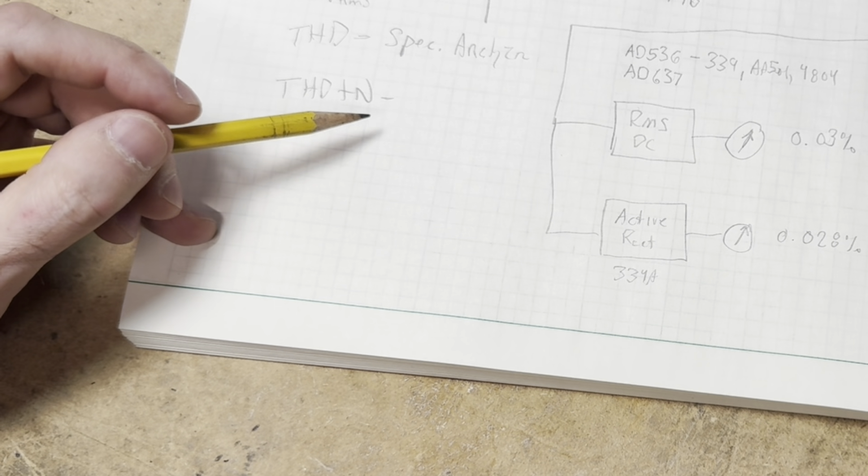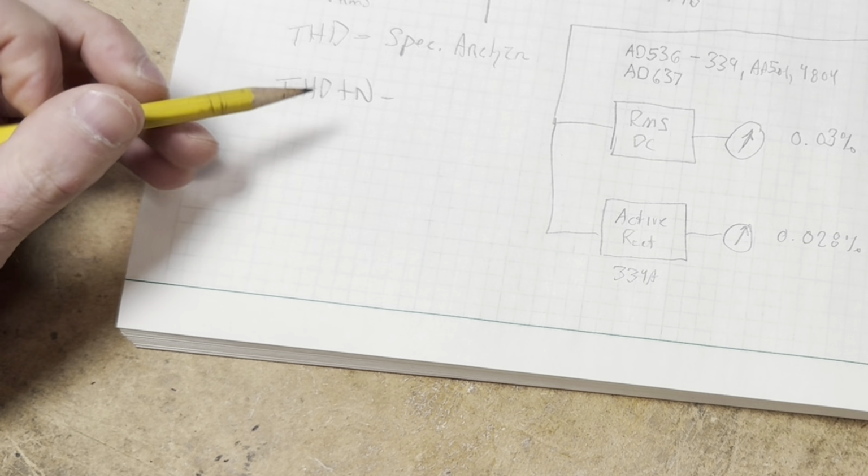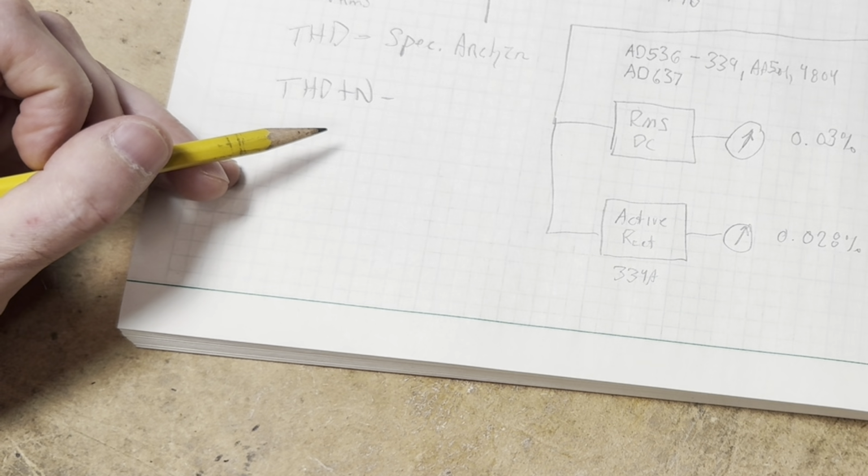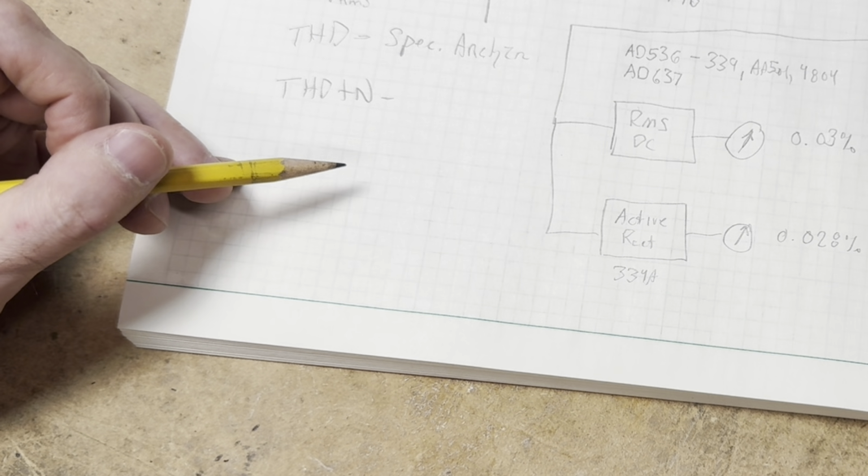We could look at a signal on a spectrum analyzer and see noise, but the noise level shown is only applicable for that one sweep of a signal, meaning that as the spectrum analyzer sweeps the signal, the noise level is changing continuously. And so that measurement, the harmonic distortion plus the signal due to noise, is changing continuously.